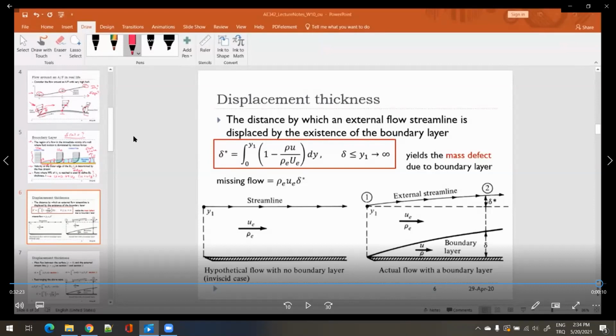Yes. The boundary layer phenomena, how does the boundary layer develop? Does it change? I mean, the flow could be subsonic or supersonic, but in all cases, in reality, I mean, in this class we are right now focusing on low subsonic incompressible flow, but in reality, let's say you are flying at a Mach number that is above Mach critical, yes? There will be, let's say, a supersonic pocket over the airfoil, yeah? There will still be a boundary layer, okay? There will still be a boundary layer.